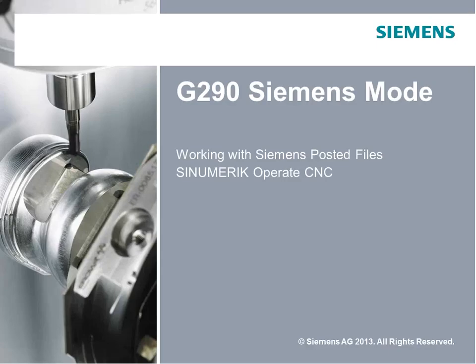So first thing we're going to do is start looking at our G290 mode, which is what we call our Siemens mode. Generally, a lot of people don't realize it, but whenever you're in the Siemens protocol, and when I say Siemens protocol, it's just really what the commands are, how they affect the machine, you're actually running in G290 mode, so you'll hear me refer to it as G290 mode. Typically, you don't have to actually tell it to be in G290 mode. The system does it all automatically, but you could in your part program if you wanted to.